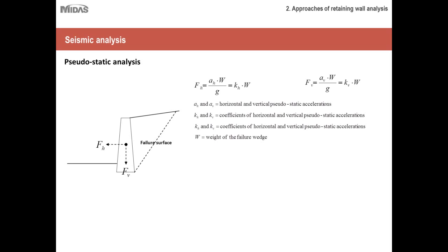So let's go into a little more detail about what these methods are and their formulation. In pseudostatic analysis, as you can see, it basically computes the weight by gravity times acceleration in the horizontal direction. So this is basically the force by acceleration. It is actually the mass that you are considering that is acting onto the wall depending upon the angle of the face.